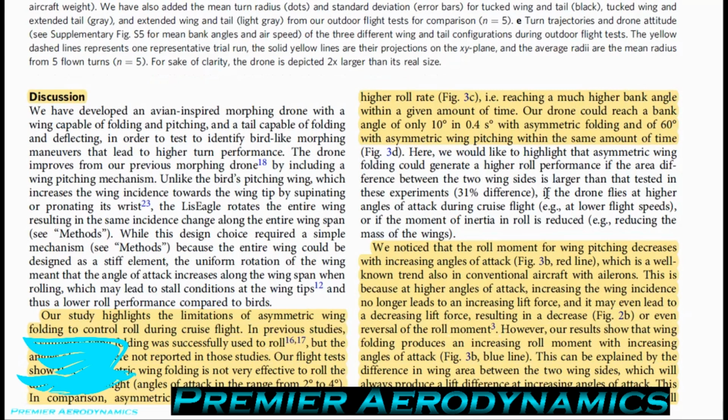So they noticed that the roll moment for wing pitching decreases with increasing angles of attack, which is a well-known trend also in conventional aircraft with ailerons. This is because at high angles of attack, increasing the wing incidence no longer leads to an increasing lift force, and it may even lead to a decreasing lift force, resulting in a decrease or even reverse of roll moment. That's because you're now stalling one side of your airplane.